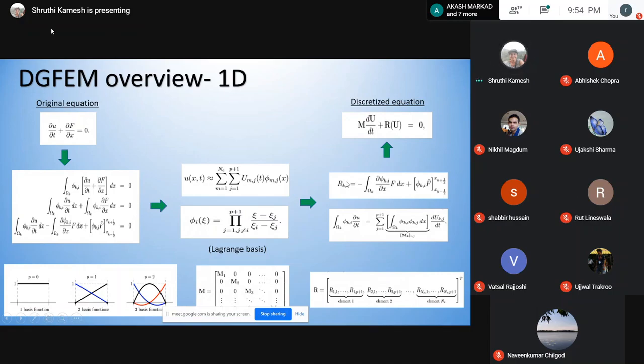And for each element, this is what is done. Once you solve the entire equation as a whole, that is for n elements, you have a global mass matrix. Each of these smaller ones, M_k_ij, is a contribution to a local mass matrix, which is M_k, and then you assemble it all together, which is the global mass matrix.